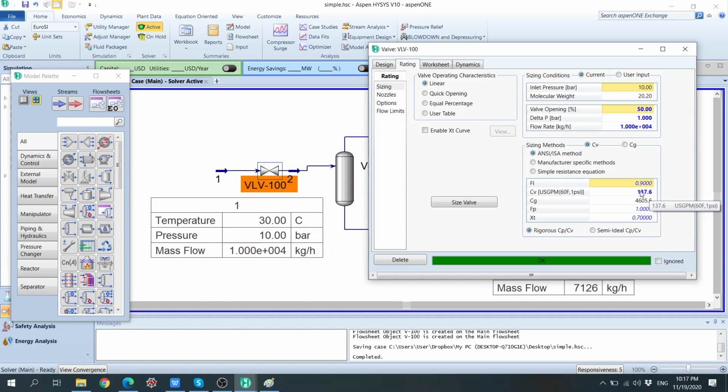You can leave it as it is, or you can go to the catalog and see what the correct CV is, whether there is a CV close to this number, or if the closest is 140 or 145, that's all up to you. For example, you can put 145, and then at 145 it will open 50%.